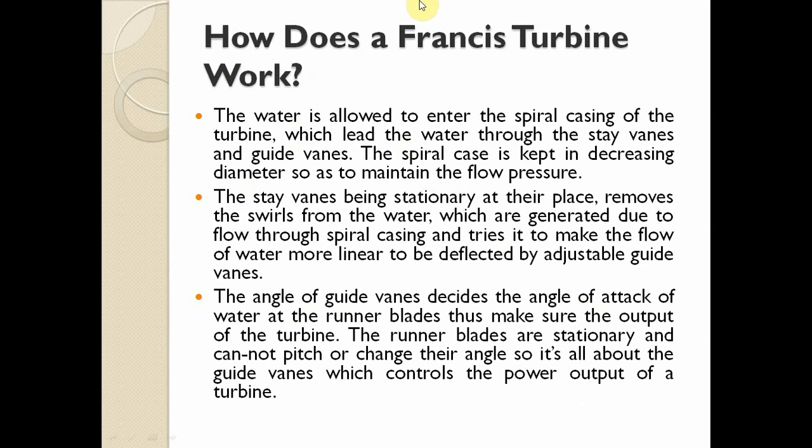So next one is, how does a Francis turbine work? The water is allowed to enter the spiral casing of the turbine, which leads the water through the stay vanes and guide vanes. The spiral casing is kept in decreasing diameter so as to maintain flow pressure.